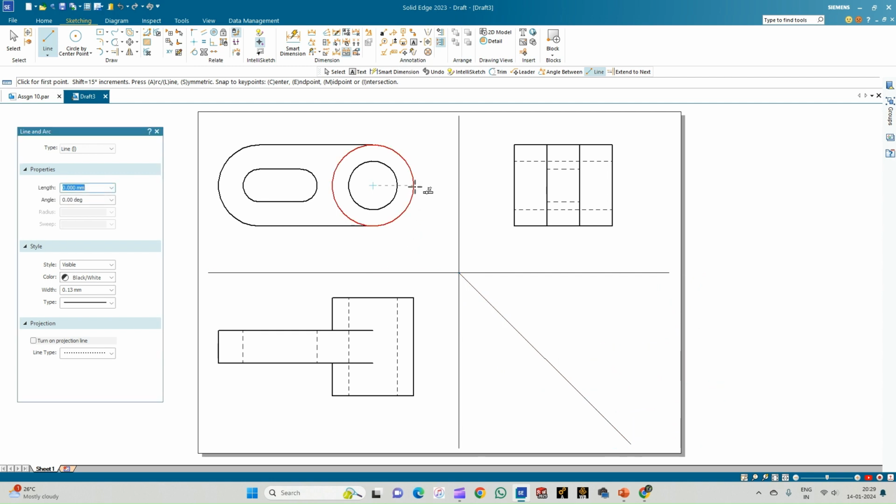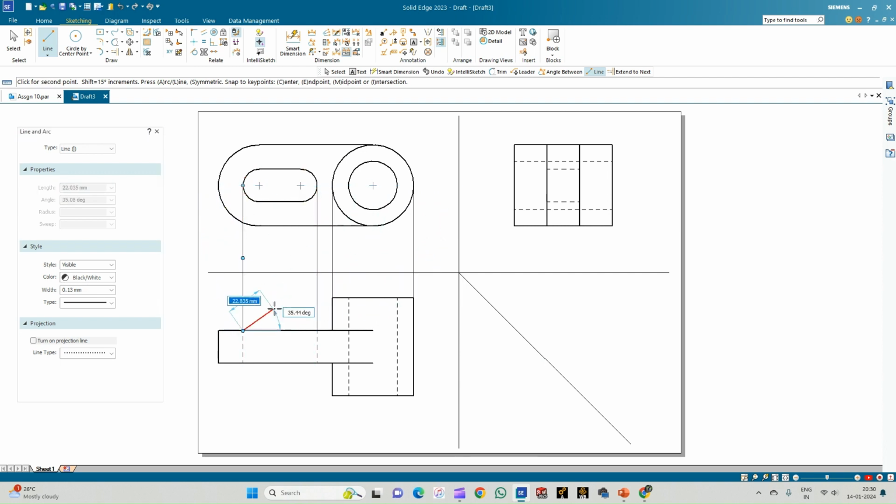So now let us fix the front and the top views. So these are the projectors. The dotted lines indicate it is a through hole, and this is the extreme left projector, completing the total height of the part. And then you can just draw a line from the center to show that the center of this part is exactly lying on the origin of this circle. Correct? So this completes the front and the top view projected.